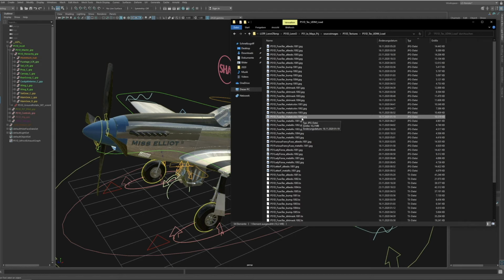You can set the default color for everything that is not mapped by a UDIM tile. So if the renderer sees that this goes to 4, but there's no UDIM tile 5, it's just going to use your default color, so you can tell it to just use black or just use white, depending on what you need. So missing tiles are not a problem. I could have for some reason not had tiles 1002 and 3 on the dirt mask if I didn't need that, so that's okay.